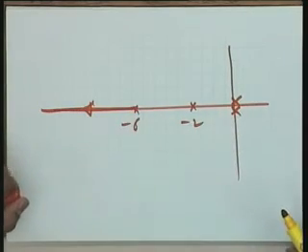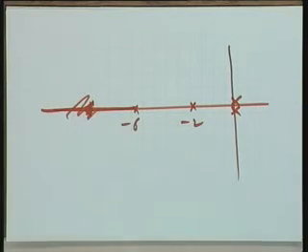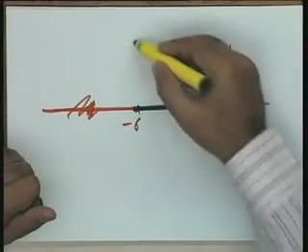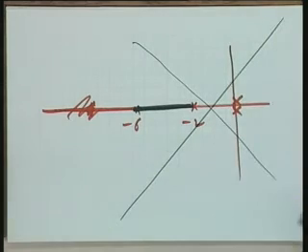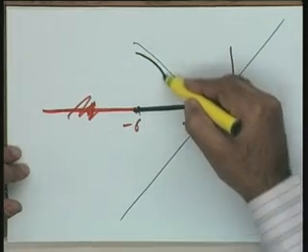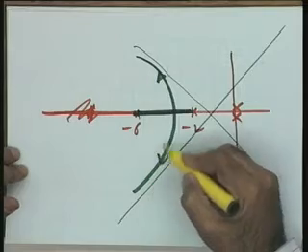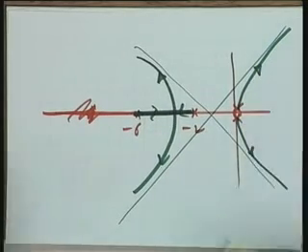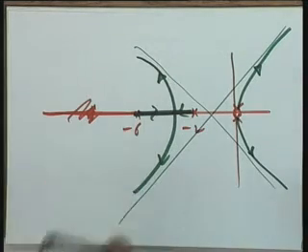This goes over here? No, this doesn't go there. Yes, tell me, where will it go? This is there on the root locus. So there will be a breakaway point here. Actually, as I told you, asymptotes are required for you to make an idea. Without the asymptotes, it was becoming difficult for you. Now maybe you can get an idea. This is as far as the two root locus branches are concerned, and here these are the two. You have destabilized the system completely for all values of k. In the process of giving Kv equal to infinity, you have destabilized the system completely.